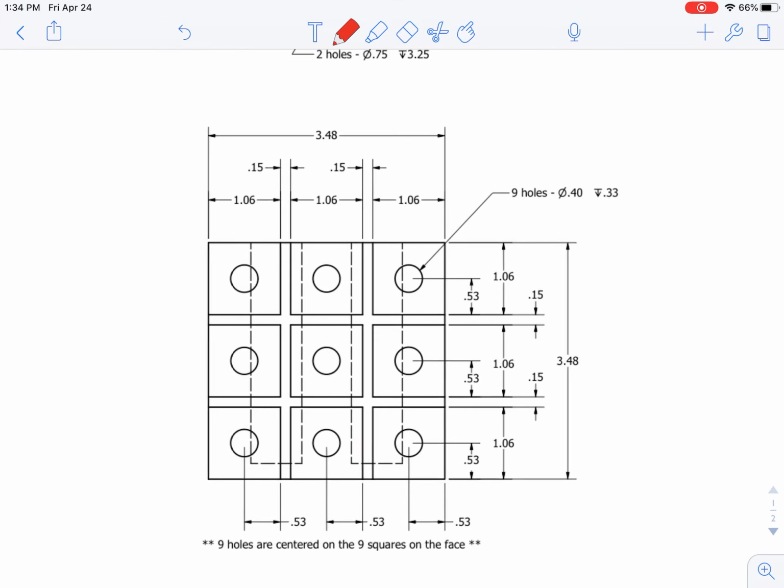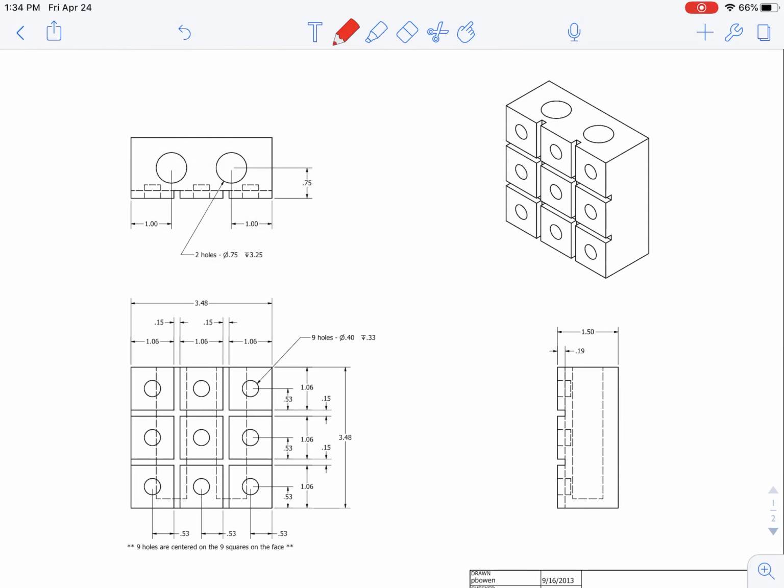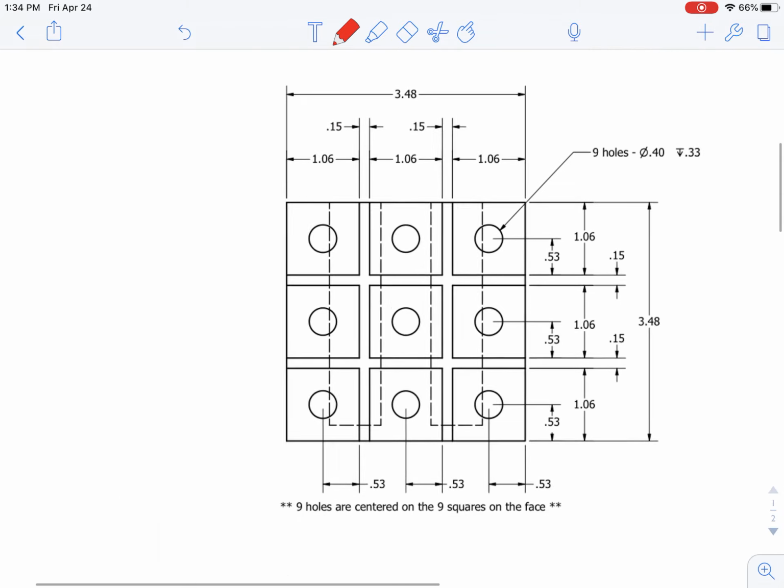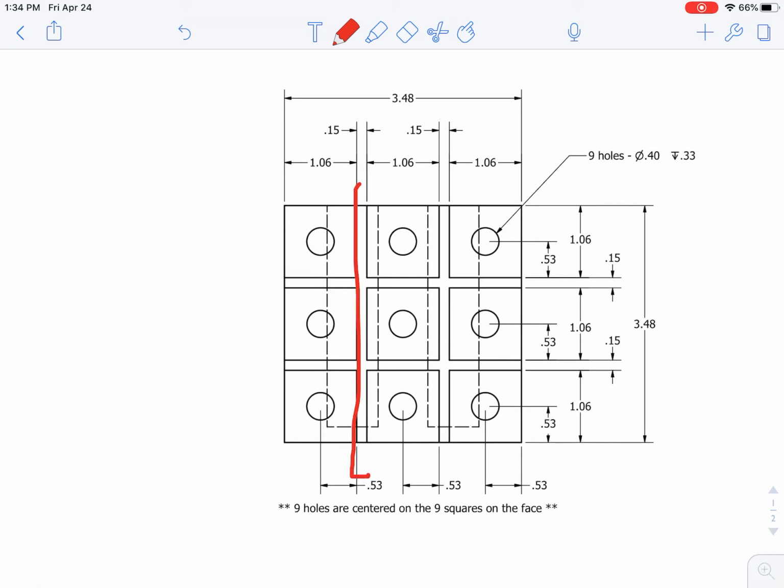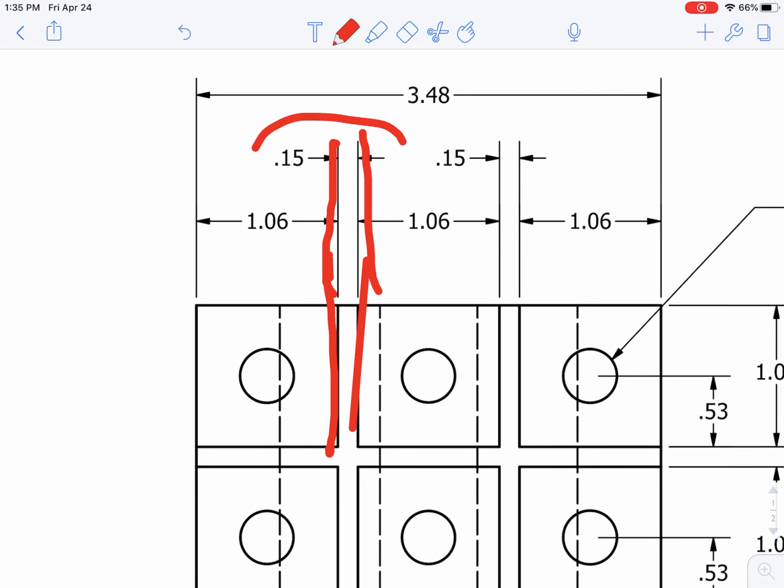Looking at our technical sketch, we're trying to draw these two grooves. So on the front view, we're going to try and draw a rectangle in that position at about that size. What we need to figure out is how wide is it from one side to the other, and if you carry those up a little farther, you'll see the arrows pointing to both lines tell you that the distance for the width is 0.15.